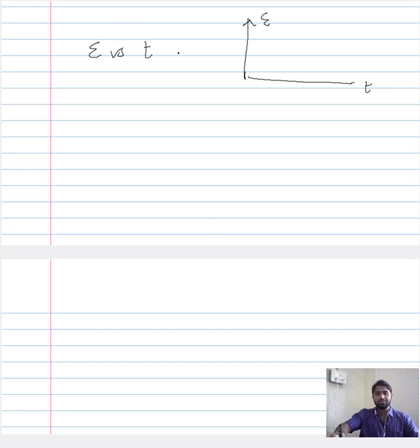So when we consider this two-dimensional plot involving the strain and time, what we implicitly mean is that the mechanical condition in terms of stress with respect to the instantaneous area is assumed to be constant all through the testing period. Now we also saw that from this conventional plot, we can arrive at the creep rate versus time plot.